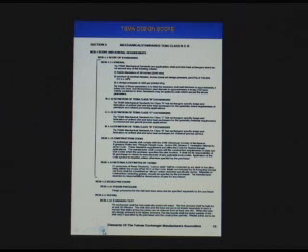Further down here, it talks about the construction codes. Typically, ASME code is applicable. Under material terms of conditions or definition of terms, all of the code materials that we utilize have to be listed in ASME code section 8 or section 1. We would utilize the allowable stresses that are indicated.